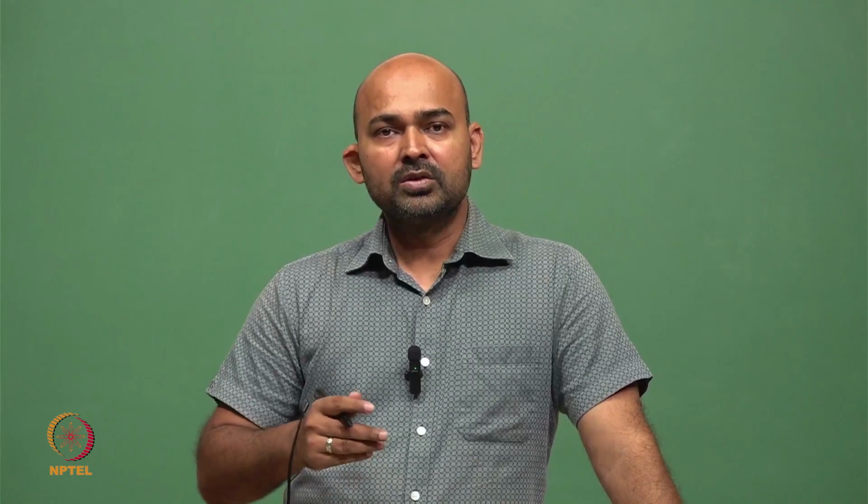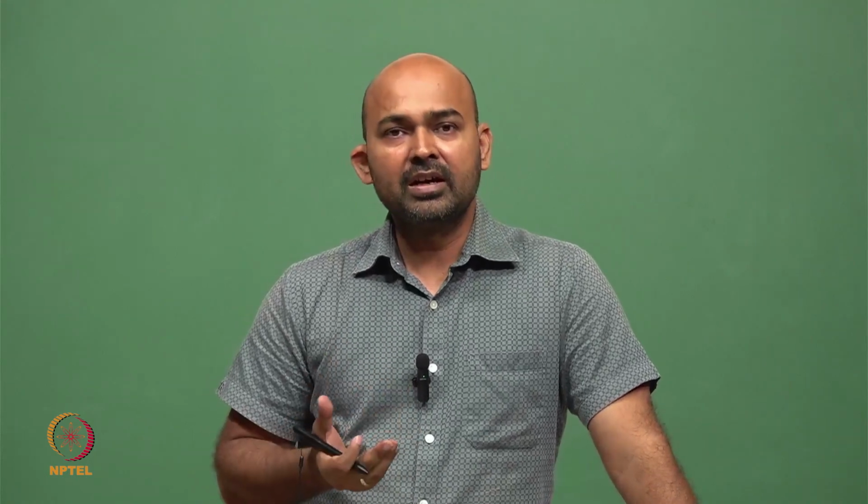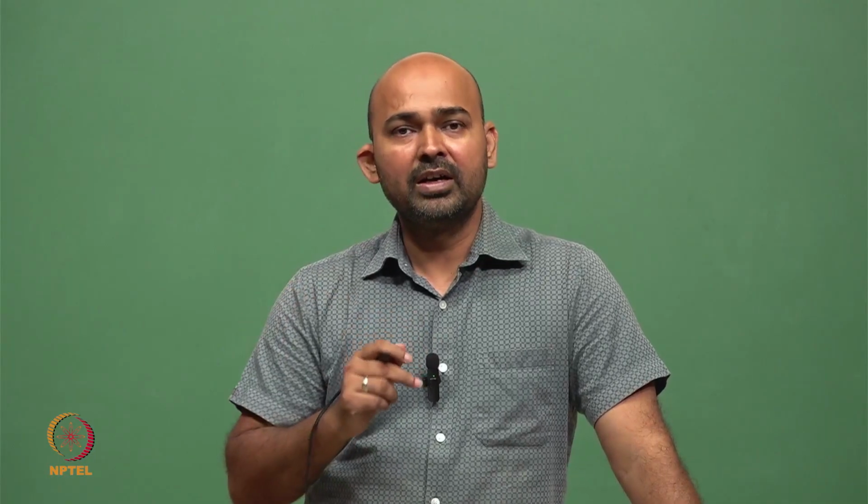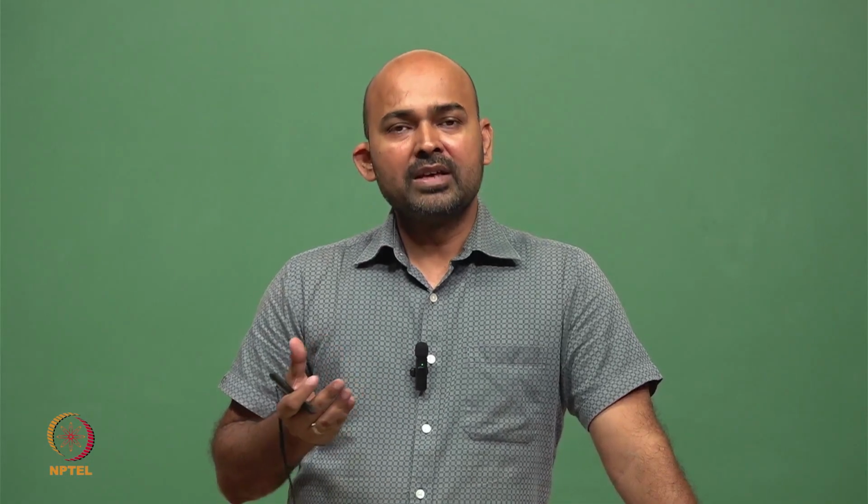Either we increase the current I. So if we increase the current, which means we have to apply a high voltage and get more current, it means the power dissipation will be more in the Hall effect sensor. That is not advisable. So I also has certain limits.